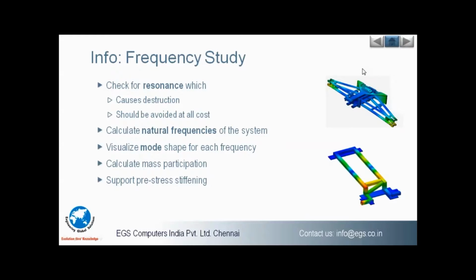Using the frequency study, we can check the resonance on the product designs, since it is going to cause destruction. So we must avoid it at any cost during the initial product design stage. Here we can calculate the natural frequencies of the system, and with everything integrated, we can directly visualize the mode shape for each and every frequency.